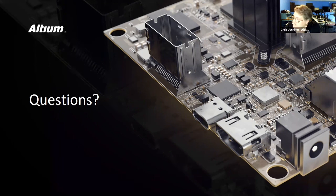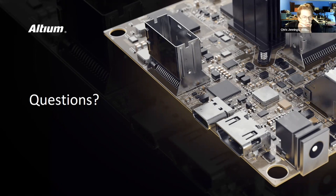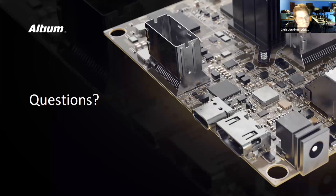Okay. So the question is about the dummy components. Dummy components basically are inactive components, which do not have any silicon die in them. So in mechanical testing, we just have these components without a silicon die because it's costly. And what do you use them for? Actually, we use this for vibration testing, thermal cycling, mechanical testing. Yep.